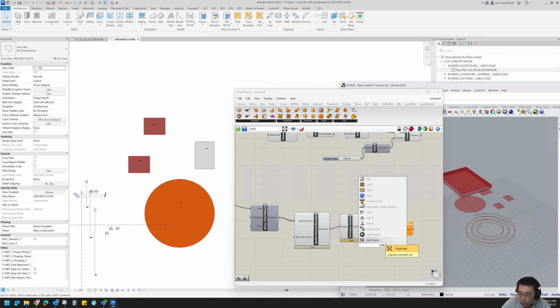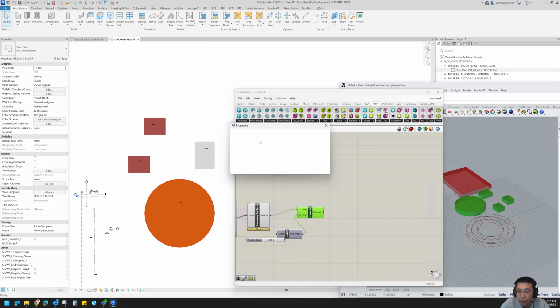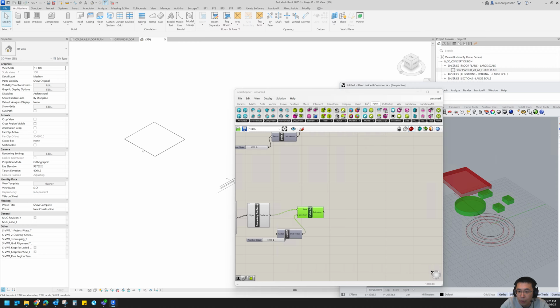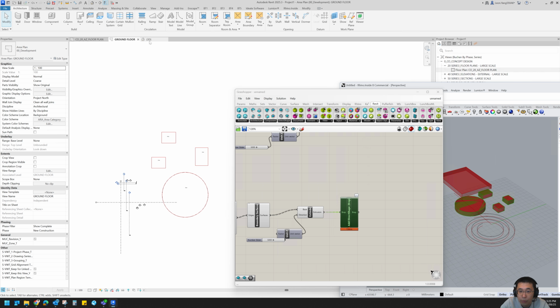Unit, say height will be 5 meters. We got these extrusions, and then as mentioned previously in the Revit, if we go to 3D, we can add Direct Shape, add DirectShape, and grab all this massing we just created from the area plan into Revit.